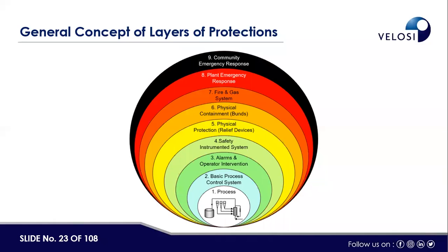Then, in the case of pressure, there are PSVs. For example, if the alarm is not attended and the SIF is not acting, then at least the pressure safety valve should be able to pop open and the fluid should be able to go out. Similarly, in tank farm areas, to contain the leakage of a tank within a specified area, bunds and tank dikes are made, which prevent the extra spread of the major hydrocarbon or chemical stored inside the big tank.